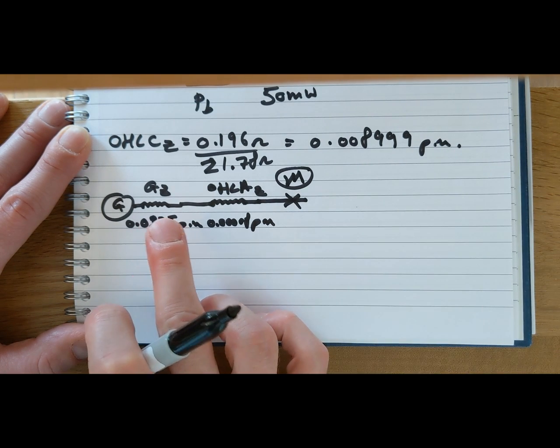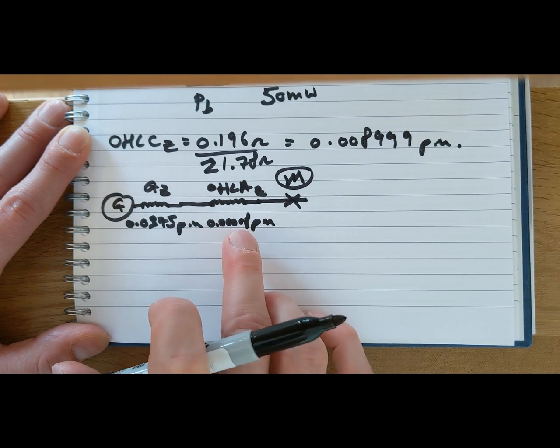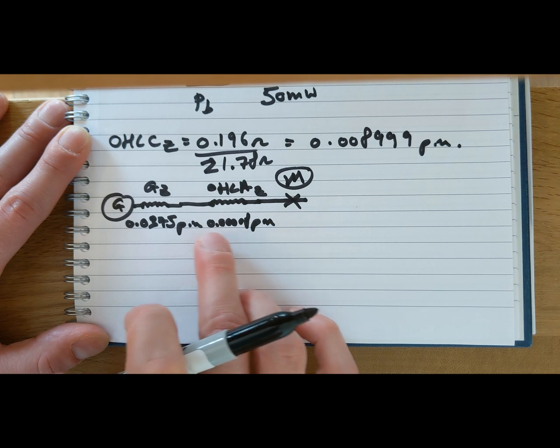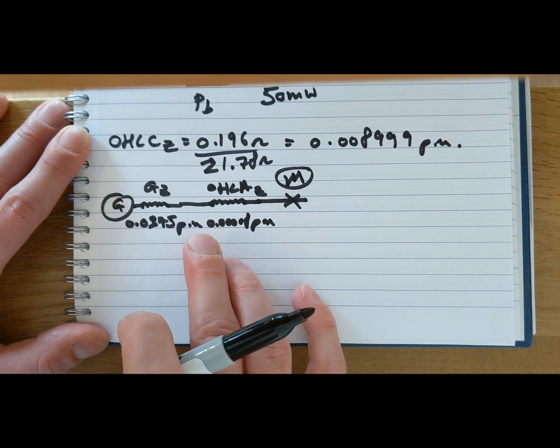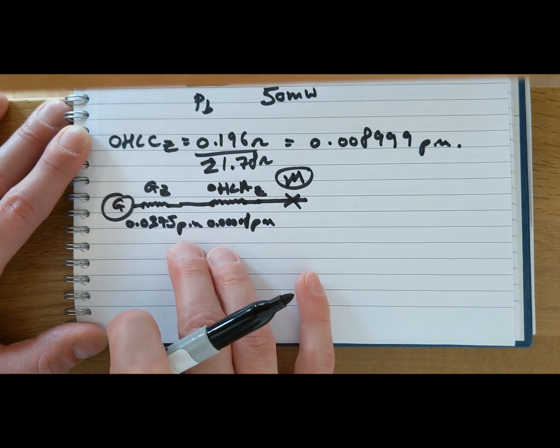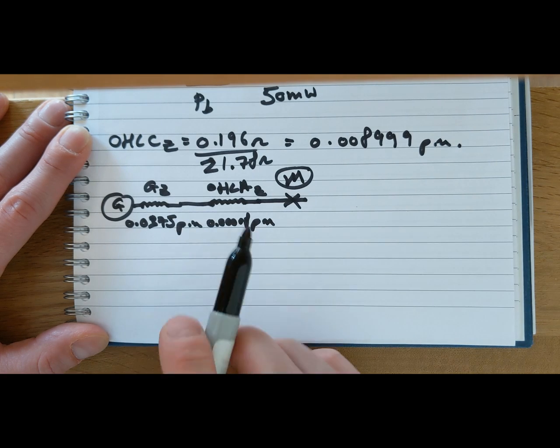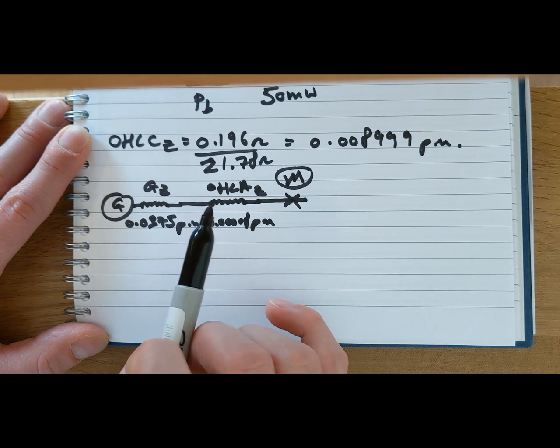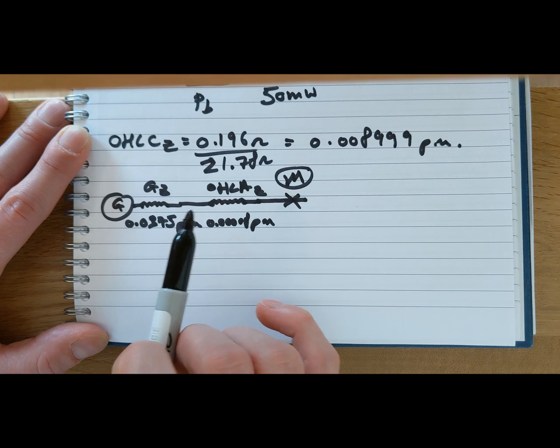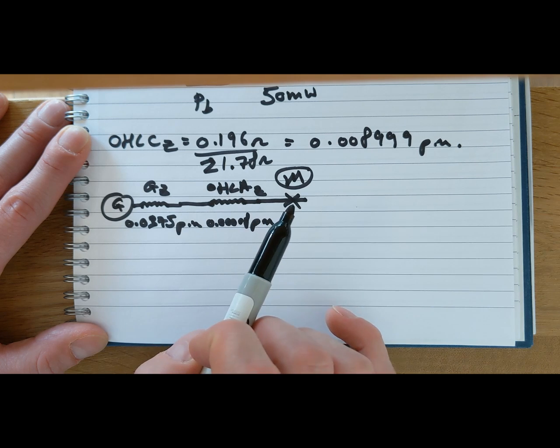And as you can see, now we've put things in per unit, and the turns ratio of the transformers has been taken into account in the bases of this per unit system. We can basically neglect the transformers. You can see we haven't written the first transformer, and we're not going to write the second either.